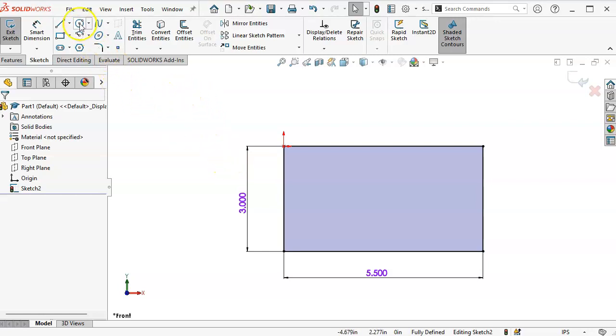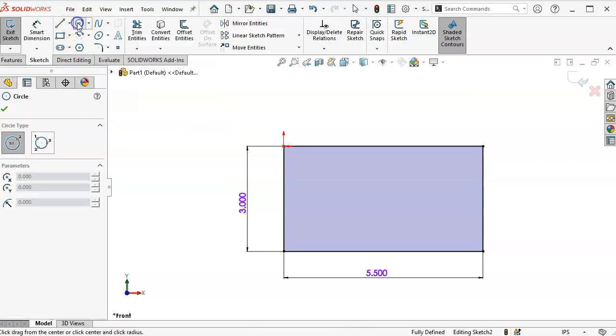So going up to the circle, and we mentioned before we had the circle, the perimeter circle. I don't need to push the arrow except to maybe familiarize with what's underneath. I click on the circle. We're kind of looking to see if there's any inferences. Not really grabbing any. There we go. And say there's one and there's one. So if I utilize those inferences, then it will show me that I'm at the center of the part, but the little boxes, horizontal and vertical, are not yellow. They're in white.